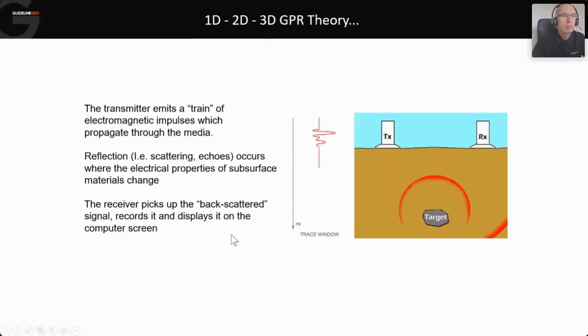As time goes on, that will start to radiate backwards towards the surface, and eventually, nothing happened on the receive antenna, so it's a dead flat line until that point where we get that signal returning back to the receiving antenna, and we get a small response on that trace. We actually refer to that quite often as the wiggle trace. Nothing too technical there, it's a trace and it's wiggling. So that's our one recording, that's one shot of signal into the ground.